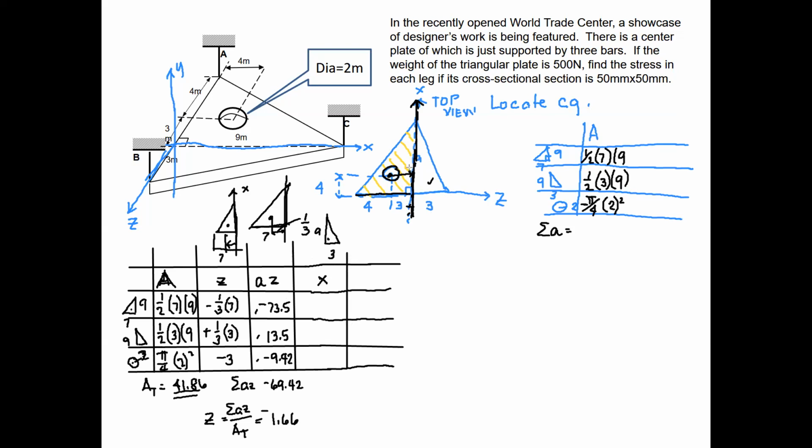How far above the z-axis? They're all above the z-axis. So the first one is how much? The centroid. This is the triangle. Its centroid is there. How far away is it from the z-axis? So that is still 1/3. 1/3 of 9. 9. Very good. Where is that from? Given. Given. Okay, but let's go to the next ones. Merluza, what about the next?